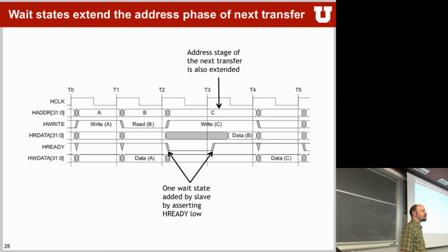Was this the one not tri-state behavior? Yes. So how does it handle? There is actually another signal, the HSELECT signal, which will select your peripheral, and there is a decoder that decodes the memory location and has a select line out to different peripherals that will tell you, this address matches you, you're selected now, you should do an operation. And they will then drive the write data into that one.